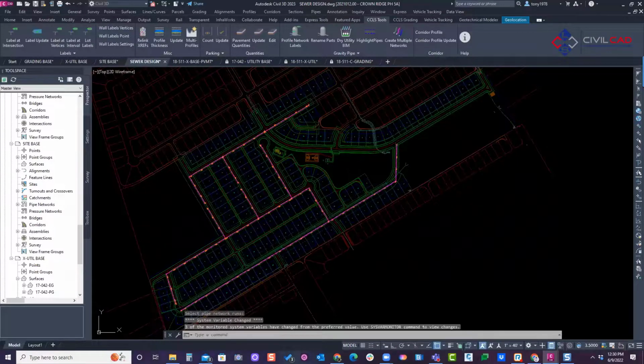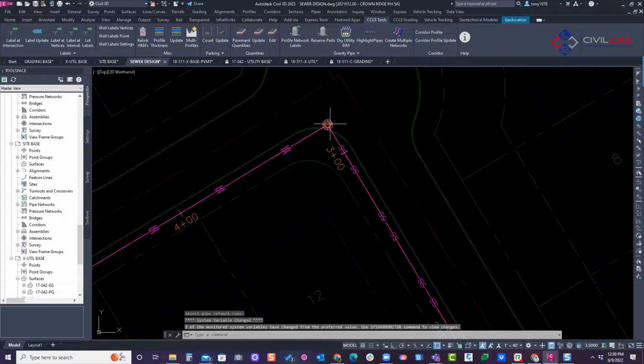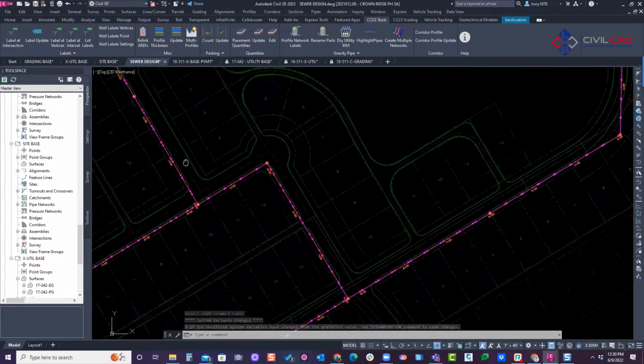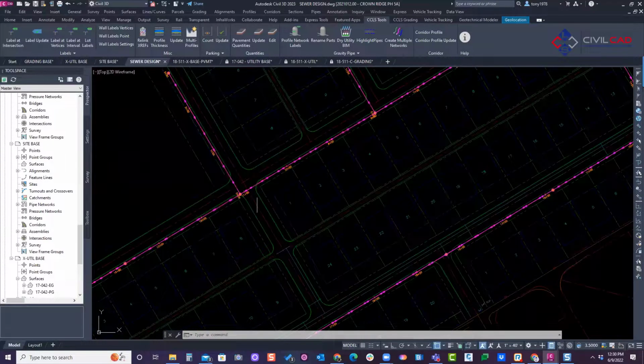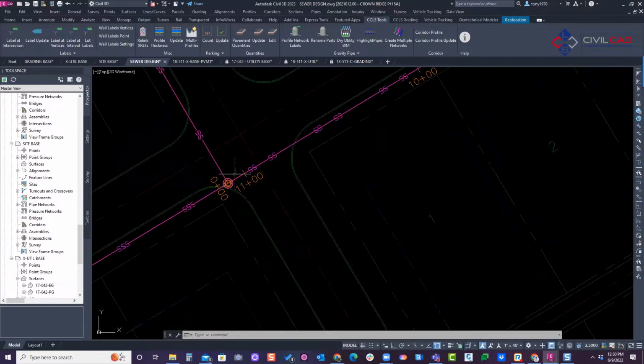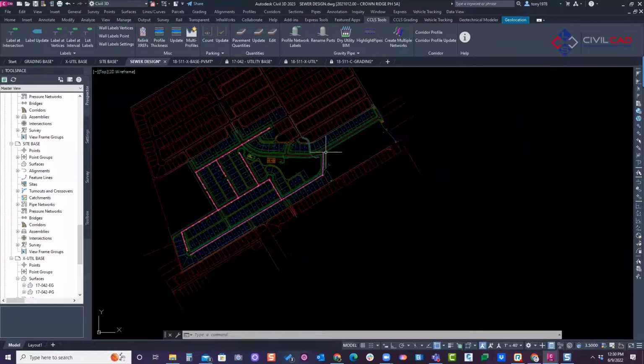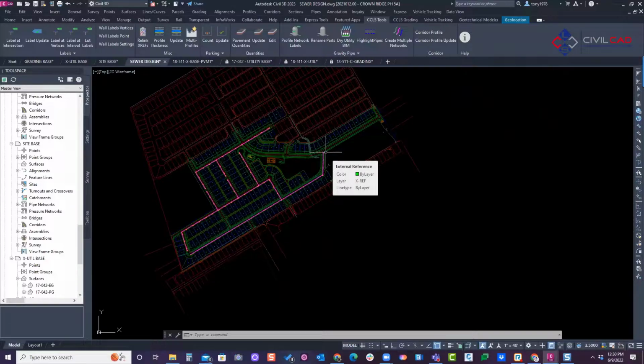And you can see it's popping up. Now you can see there's my manholes, there's my pipes. It's created every one of these. They're all created. You can see our manholes here also. And our network, so within 1 minute, we just created all our alignments and all our sewer. Now you can do this for sewer and storm. So you can actually create your storm and sewer at the same time. So we actually do that all the time. One of my clients, that's what they love about it is, hey, we're going to create our sewer, storm system, alignments, and pipe networks all at one time.